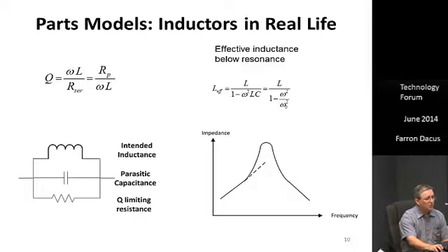Well, we can do some simple math again to show that effective inductance is once again larger than the rated inductance, and that's something that has to be taken into account in anything where you're using a signal inductor, not a choke, but a signal inductor for filtering, for a tank in a VCO, anything like that. These things have to go in your simulator.